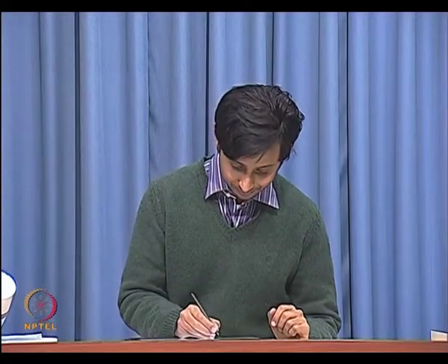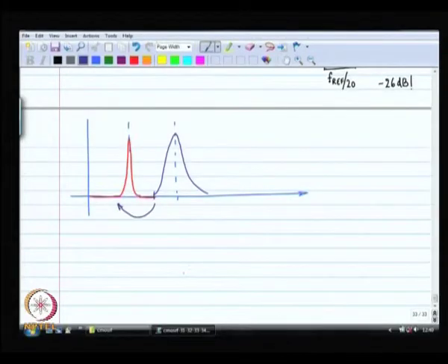So, when you divide this particular VCO output by a factor of 2, what does it mean? How is the spectrum going to look like? Any guesses? The spectrum is going to scale in the x axis by a factor of 2. So, this point will translate to this point by 2, this point will translate to this point by 2. Every point is going to translate to that point divided by a factor of 2.